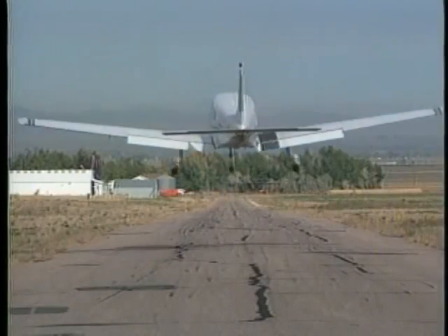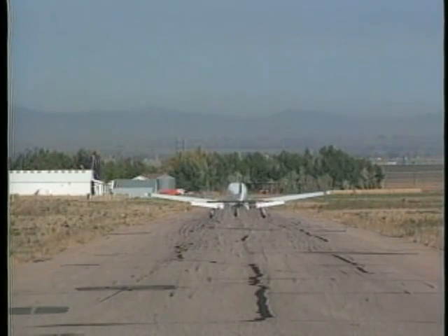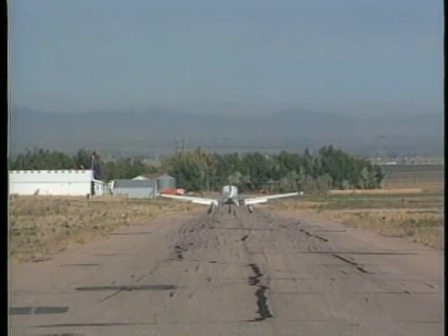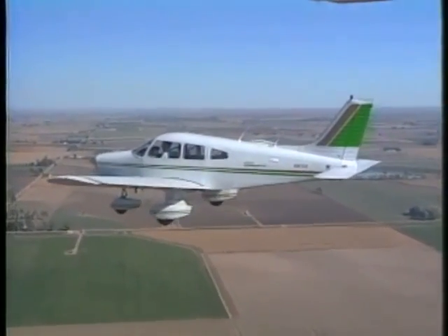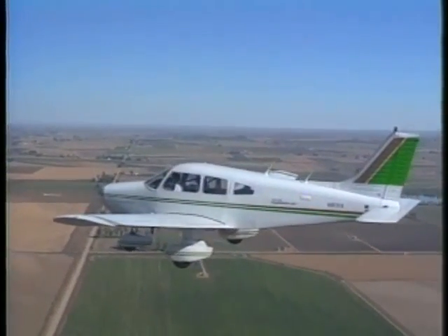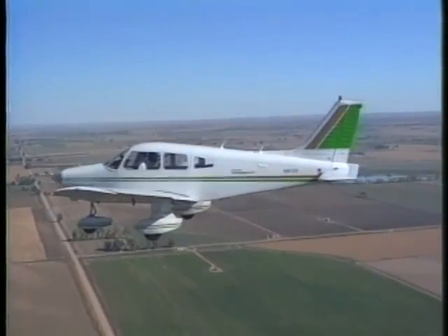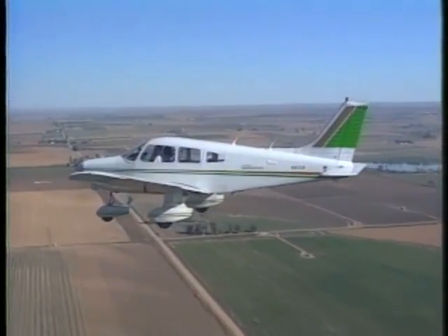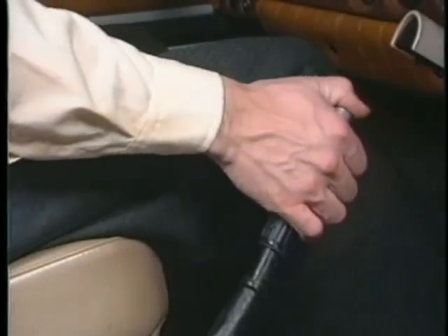Landing on a short runway, or on one which has the landing area restricted because of obstacles, requires a short field landing technique. Preparation for the landing begins on the downwind leg. There you should slow to pattern speed and extend the flaps to the first position. If your airplane is equipped with retractable gear, lower the landing gear. It's recommended that you extend the second increment of flaps while on the base leg, and full flaps when on final.